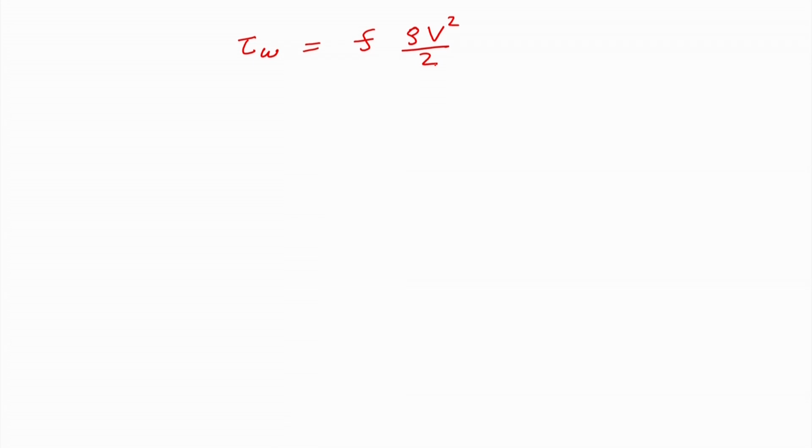For a cylindrical pipe we have written already that P upon A, with tau W, is pi d upon pi d square by 4 into tau W, which cancels out to 4 tau W upon d. But now, because the flow is separated or annular, we cannot use P as pi d, since it is not occupied in the full pipeline. So your P will also be modified. We will see how P is modified, but first we will see how to write tau Wg and tau Wl.